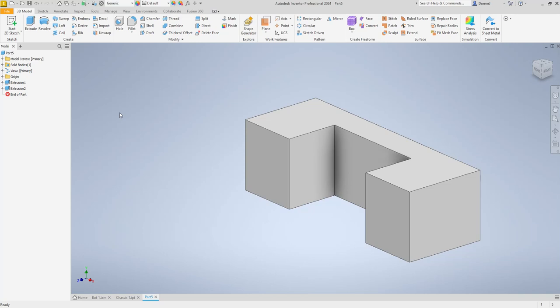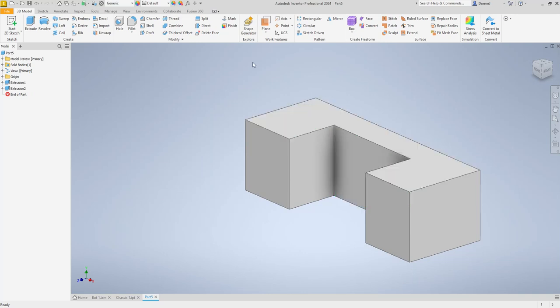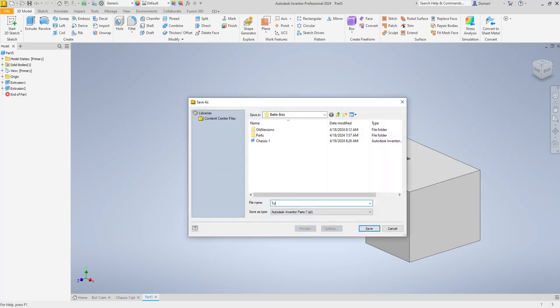Now, technically, if I want these two halves to sandwich tight on the motor, should I have the depths be the same depth as the motor, or a little less, or a little more? Theoretically, it should be a little bit less than the size. That way it actually clamps down. So I'm going to take that 0.325 depth and make it 0.320. That way it gives it tight when it comes down on the clamp. I'm going to save this as top motor clamp 1 into my folder where all my stuff is.